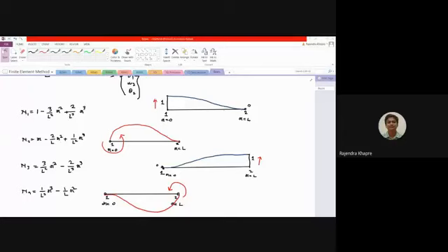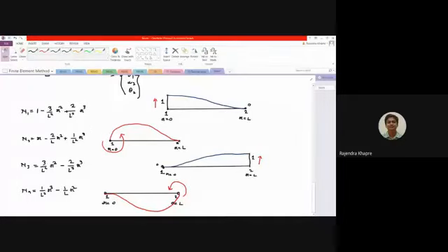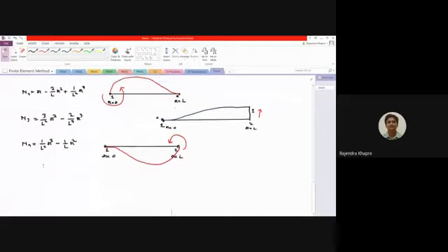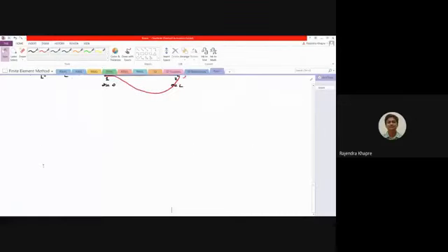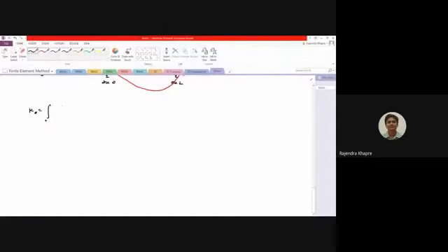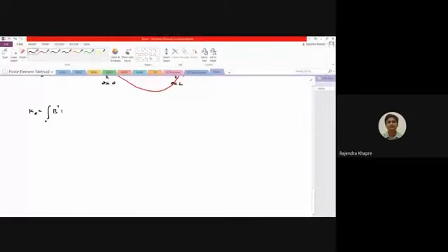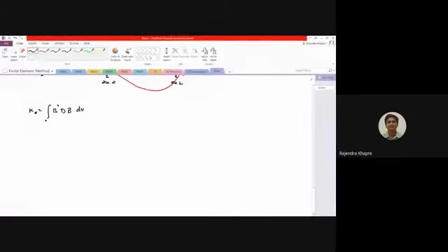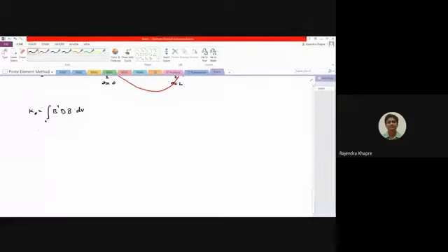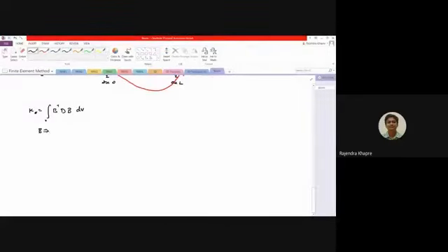All right, let us quickly see the derivation part. If you remember, to generate the stiffness matrix, we go for K elemental equals the integration over the volume of B transpose into D into B dV. This is a generalized expression which is derived from the equation of minimum potential energy. For this purpose we require the B value. B is nothing but your strain displacement matrix. For this purpose we need to calculate the strain, right?